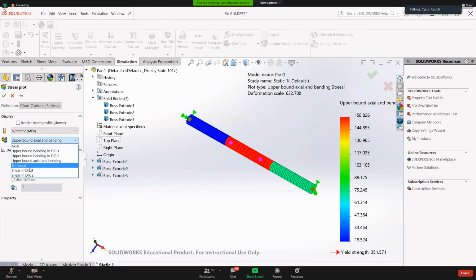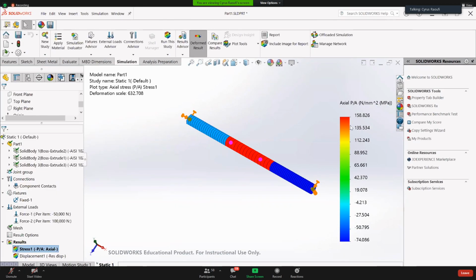And you can measure the torsion, you can measure shear. We'll talk about those in more detail the week after next, when we talk about beam. Since we simplified the problem to one direction, all I want to measure is just the axial, because if there is axial load, you should have only axial stress. And as you see, it's not a significant difference from what we had before.